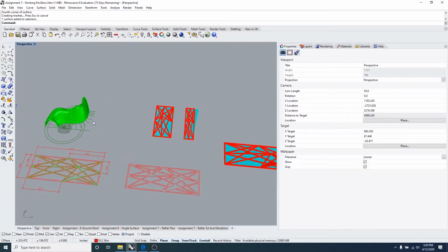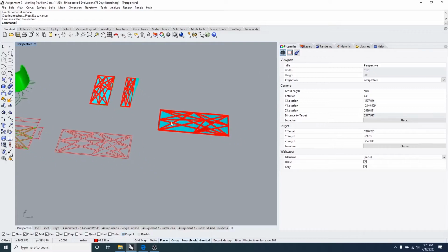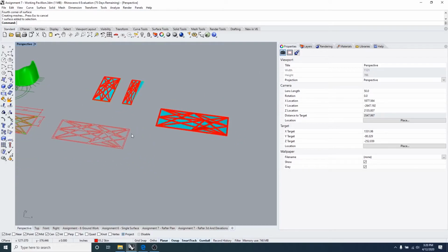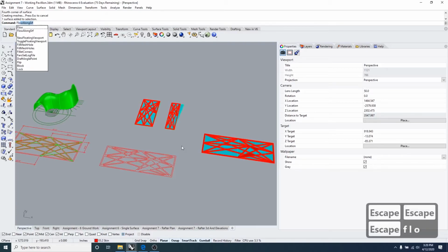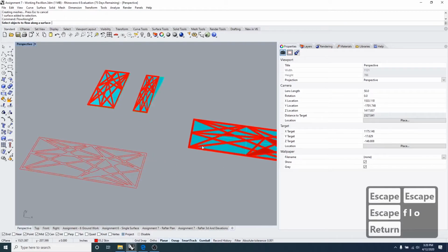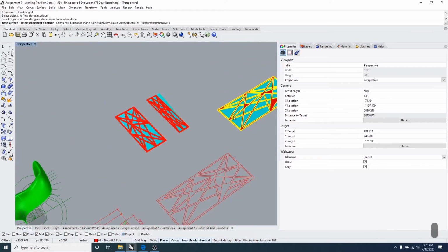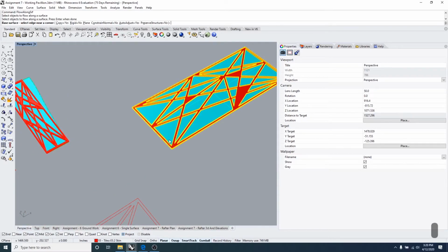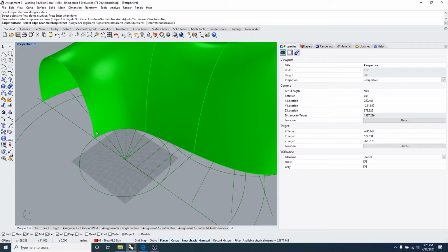and we're going to use that as our base rather than rotating it and trying to scale it to the UV curves that we did. We're just going to do a plane below. This should be easier for you guys because you don't have to do so many commands. And then just do the flow along surface. Select your panel. Pick the corner that you want to use. I'm going to pick this corner, and then I'm just going to apply it.